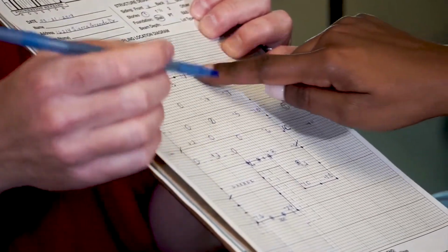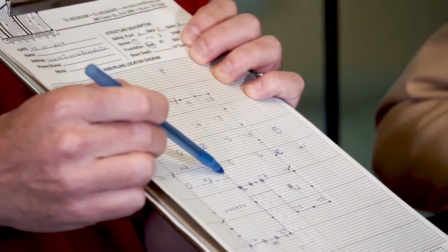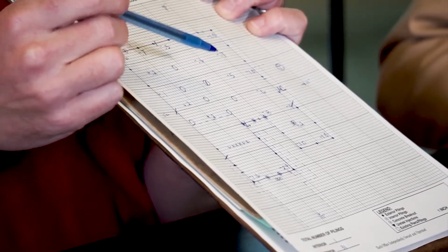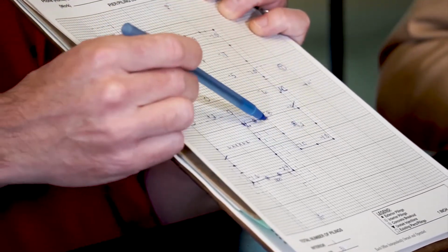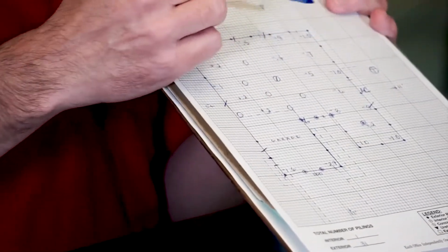Okay. Now there are dots all the way around. They're all the way around the back here. Okay. I'm kind of going stress sign to stress sign. These are just zeros, so that means that these measurements inside are even with my reference spot. But these dots that you see here and the ones that are circled just mean that we have to go through some concrete on the driveway and on the front porch. Okay. But anyway, each dot is equidistant, or as close to equidistant as I can get it. On a house like this, a 1-story, traditional home, it's gonna be about every 7 feet. On lighter structures, we might be able to go about every 8 feet. On a 2-story house, typical construction, we're gonna go about every 6 feet, okay?